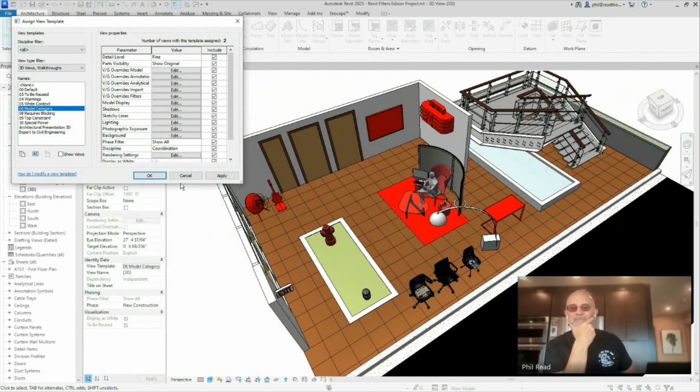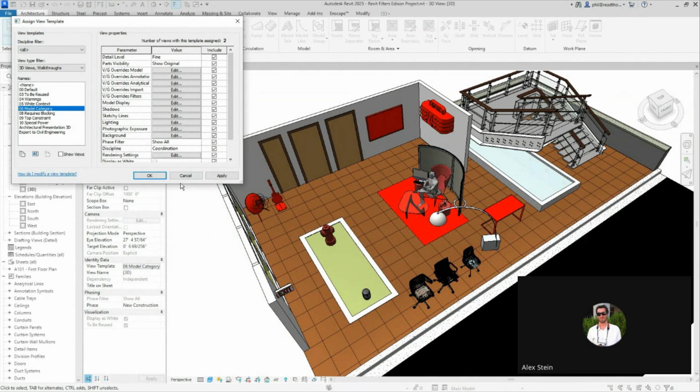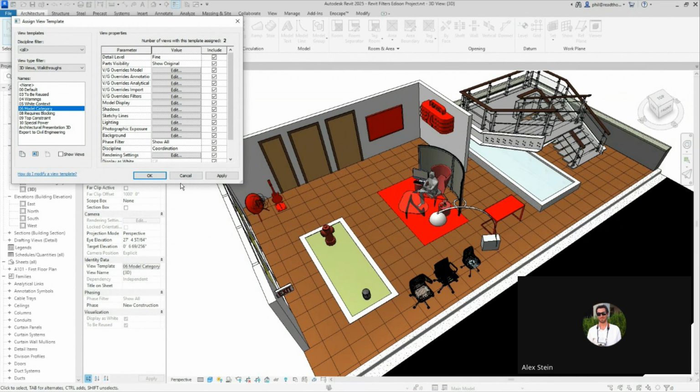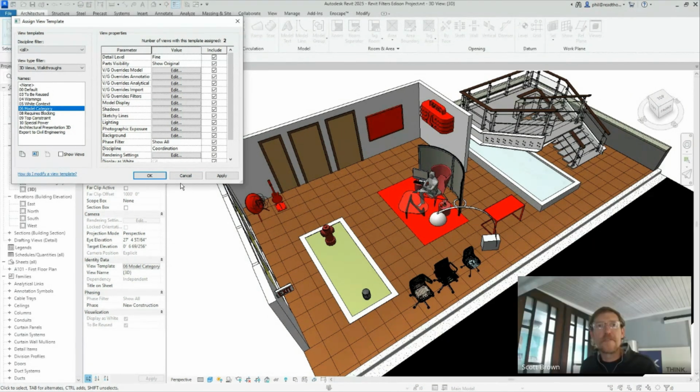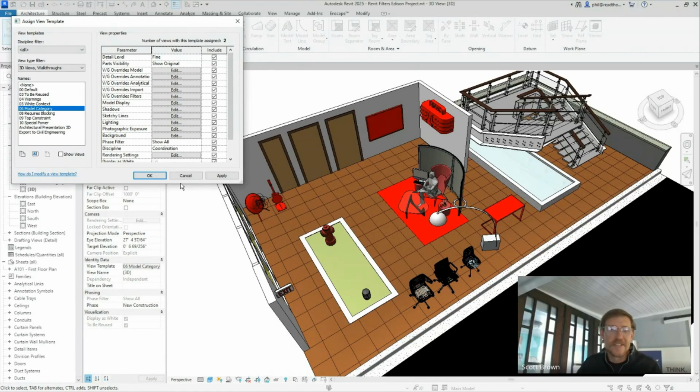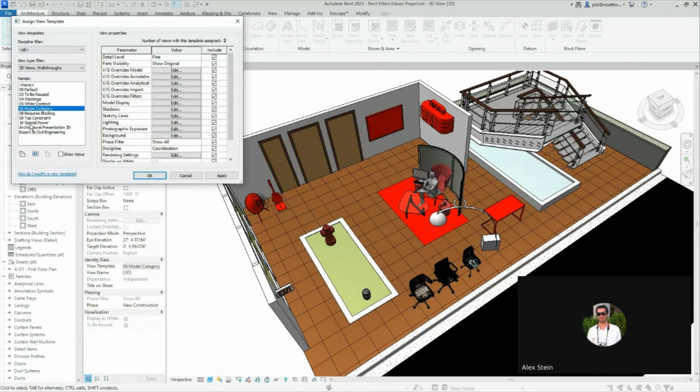Who's that being clever? This is Alex, the BIM manager. Hey, Alex, thanks. That's cool. So you could run a script to identify in-place families and update a parameter or check a box saying this is in place. Oh, right. Have it fill out its comments or something. Yeah, that's a good call. But they could ignore that, so that's not really a long-term solution.